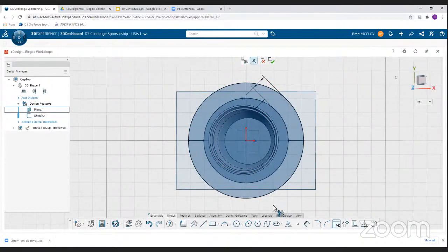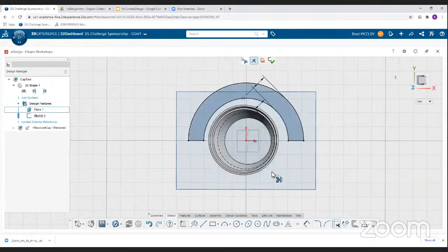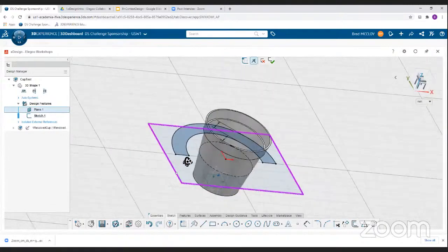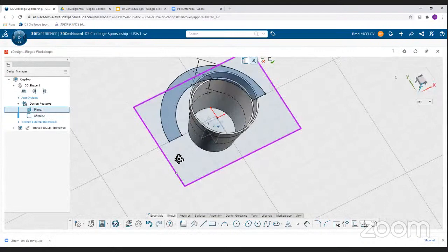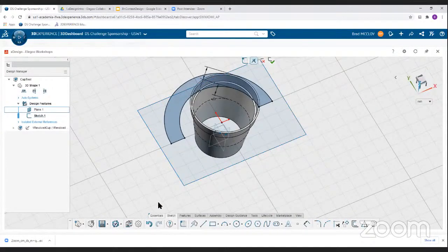So I'm going to go to the scissors tool. I'll cut that line. I cut the whole half off. I'll cut this line and cut that off. And now, if you remember, the blue color means you've got an enclosed solid. So you see the scissors right by my tool there. I'm going to press escape to get out of scissor mode. We've got something that's starting to look like a tool, but it's only a sketch.